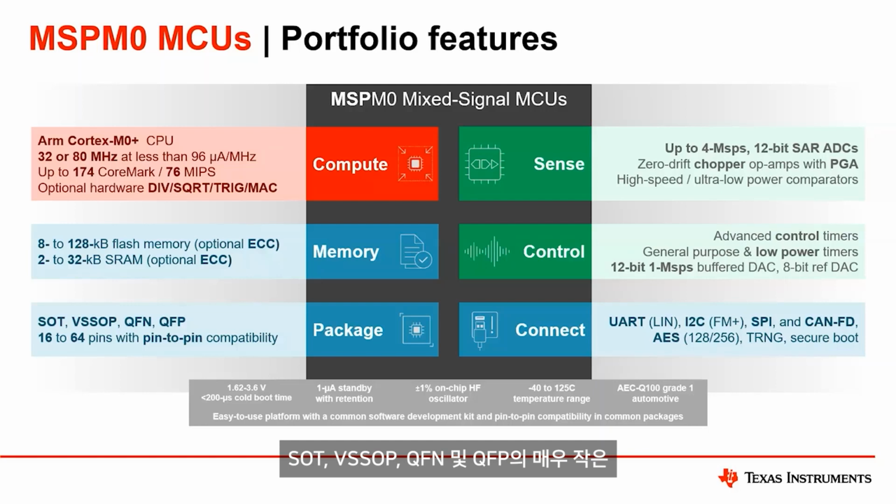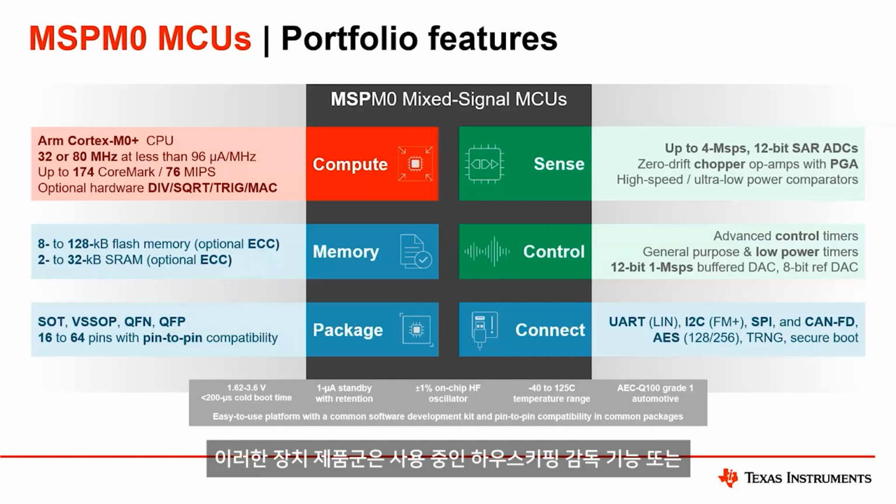We also have very small footprint packages, from SOT, VSOP, QFN, and QFP, from 16 to 64 pins with pin-to-pin compatibility. And, providing the same message, we did not just launch one device; these are families of devices, so that depending on what type of housekeeping, supervisory function, or secondary MCU application you're using, you can utilize that in your design.